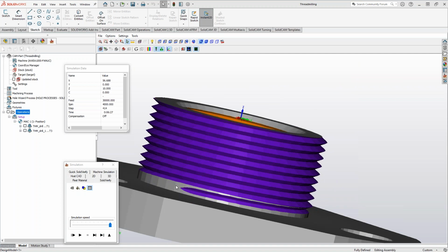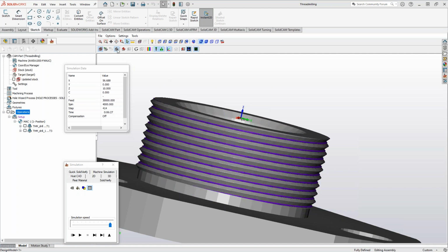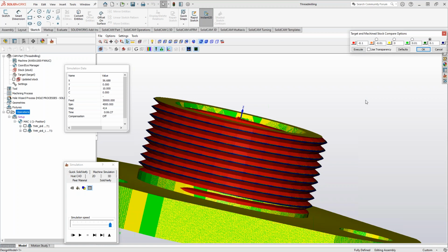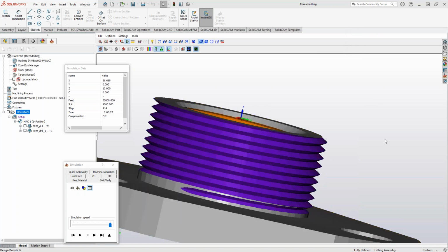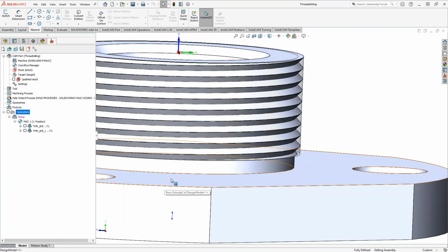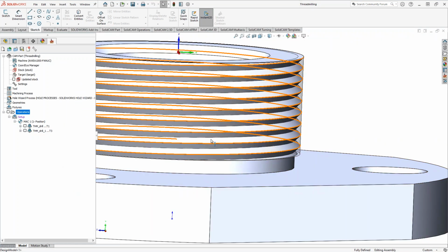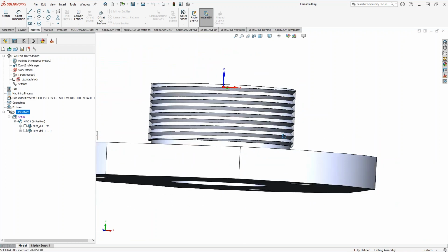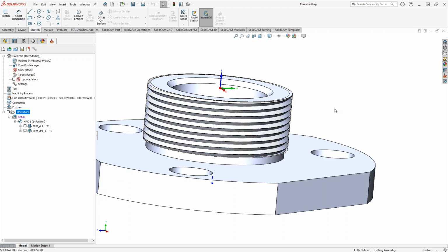But what I was mentioning before, my target actually looks like it has the thread, but they're not even in the same spot. So you get that weird cross threading. And it actually would look like a gouge. But if you want to see the thread generated by your thread mill, you want to just kind of make it look like it's some sort of cosmetic, then that's the way. Add a shape to your thread mill, and then you can get what would look like your realistic toolpath. So any questions on that?